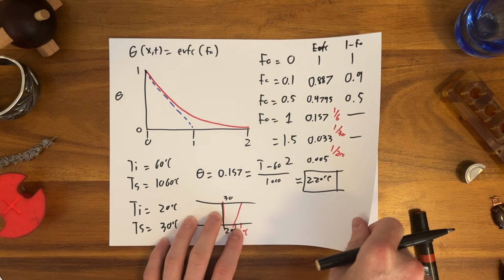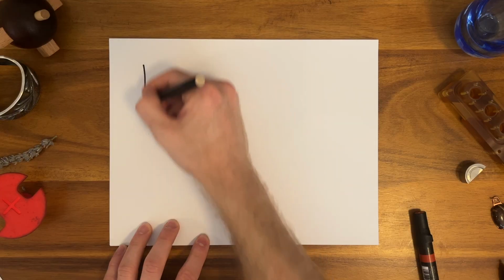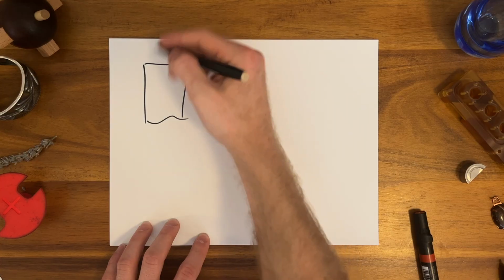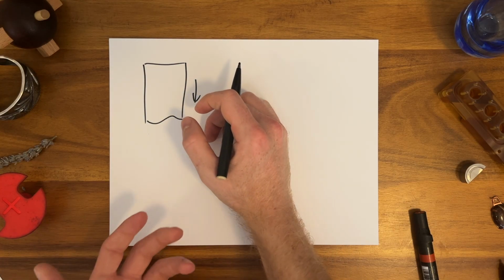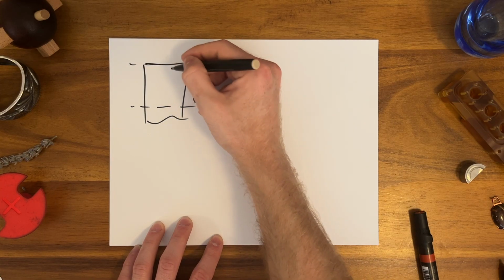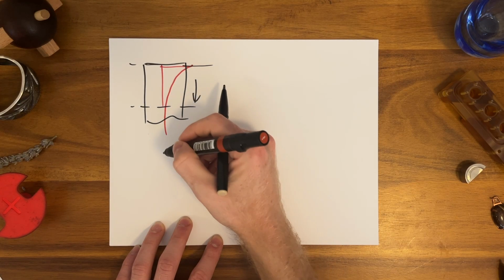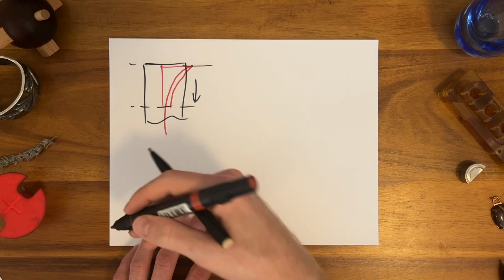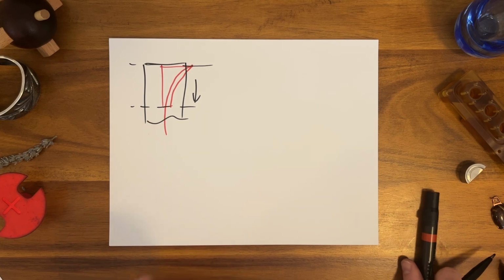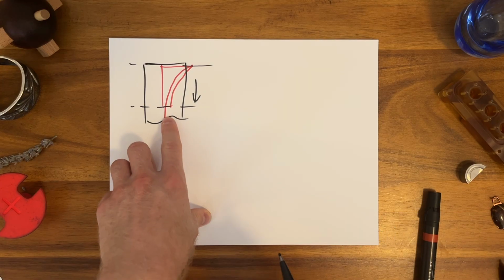And this is some good intuition to be built here, but there's a few caveats with what we're doing. We've been assuming you have an infinitely deep solid that you're then heating from the surface. The two examples I gave were definitely not infinite. They're definitely a finite block, and at some point, the heat will hit the end of the block, and instead of having that curve off to infinity, it's going to be a little bit hotter because you're actually going to eventually fill up the lumped heat capacity of the block. So if your structure is thin, like maybe 1 Fourier number or below, you're going to be a little bit under predicting when you use this.